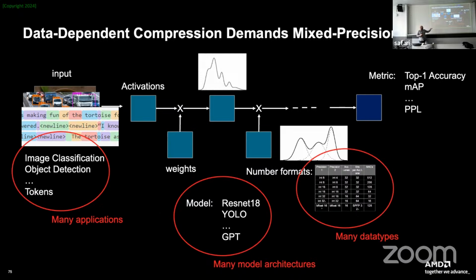You have different model architectures, and depending on the size and the number of parameters, they can be in a narrower or wider local optima. So when you quantize them, changes in your values may translate into more dramatic or less dramatic changes in the quality of your model. Therefore, we should support multiple data formats in order to cover a larger set of applications, so the hardware can be more generic.